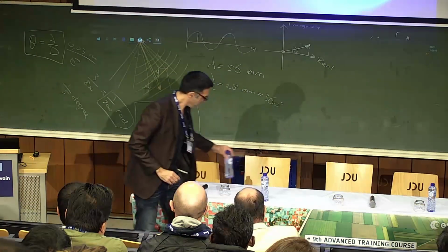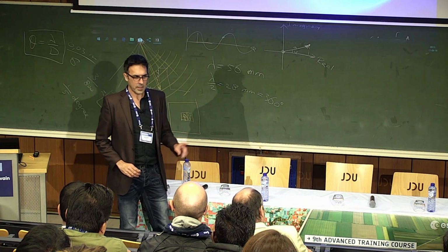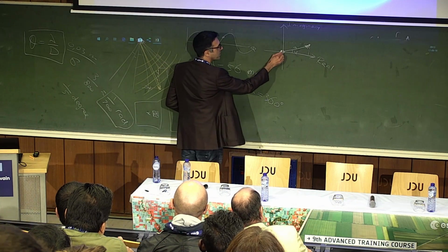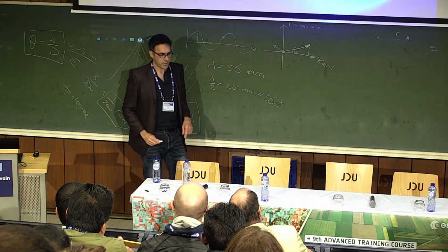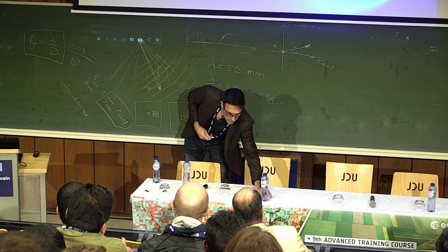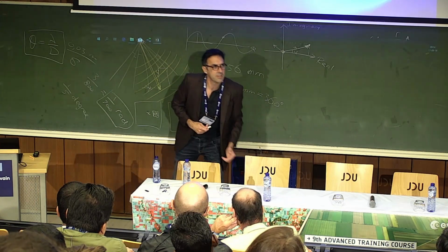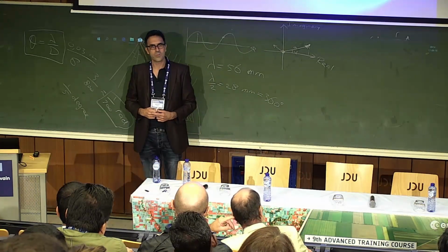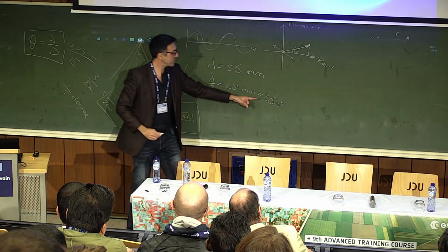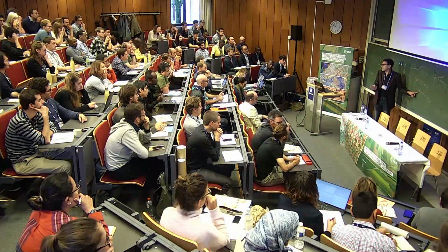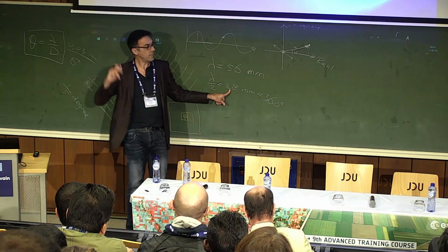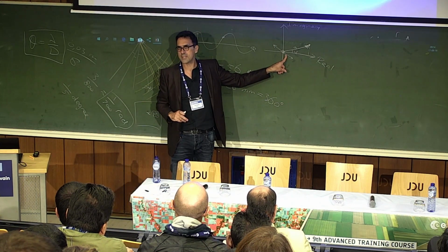So let's put this bottle away. I was talking about this one. So I will get an arbitrary value here. Maybe this one. Right? Now, if I would roll back time and move my bottle this much, what would the phase do? It would rotate almost 180 degrees, right? It would be here, right? Because 360 degrees is 28 millimeters. I shifted it maybe a centimeter or so. So this distance difference from the bottle to the satellite now has a huge effect on the phase.